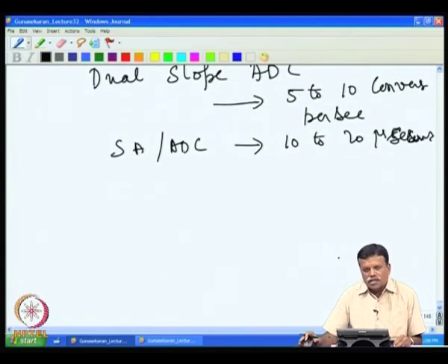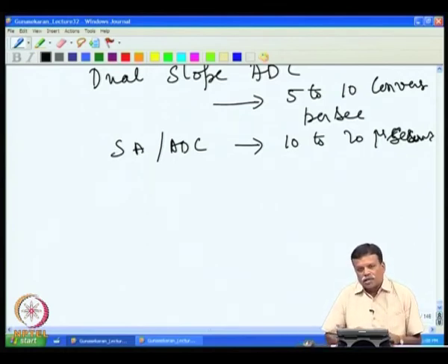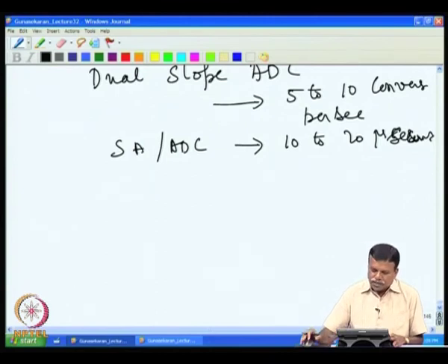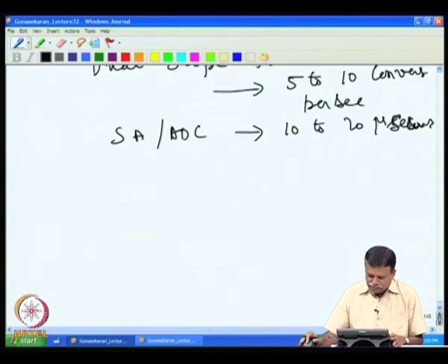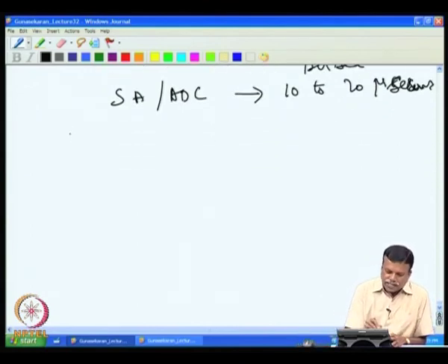If we want to get to a nanosecond level of conversion time, then successive approximation ADC is not the correct choice, because it becomes very slow, as it has to go for 8 trials for 8-bit converters, and also it has to wait for the sample and hold to acquire the required voltage. This problem is not there in the flash ADC converters.